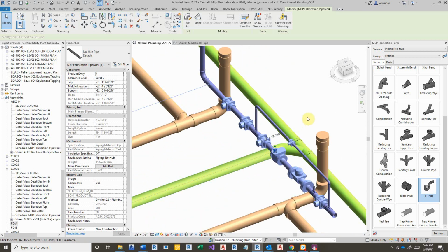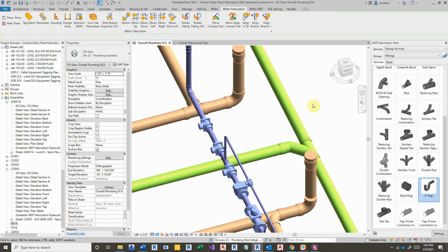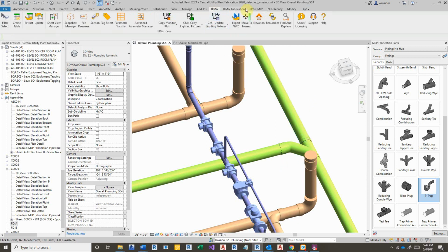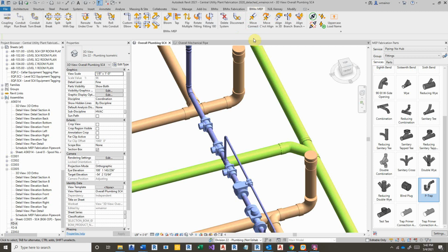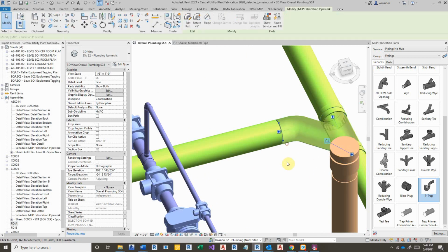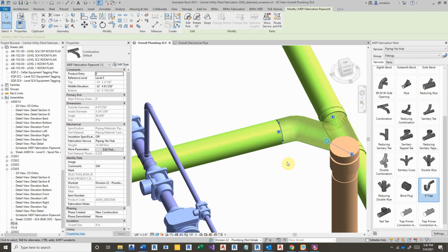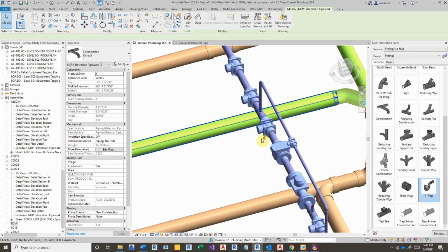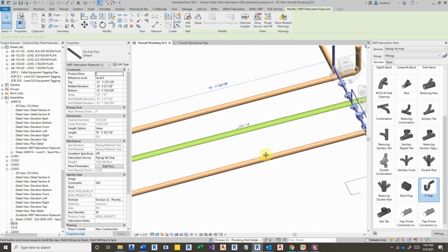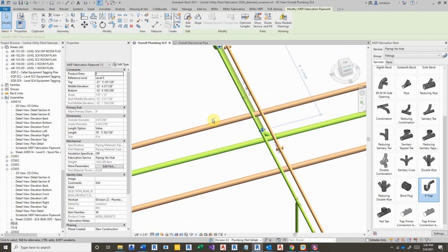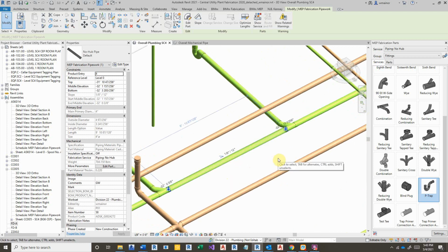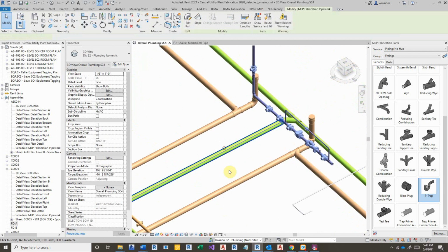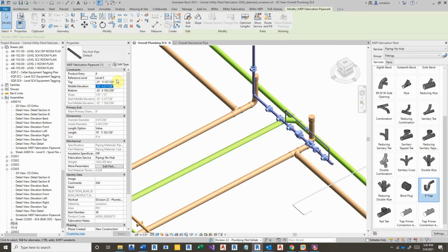because we have tools that are going to allow us to break connections. So we've got a disconnect command on BIMrx MEP that allows me to come in and click on two fittings, and it breaks the connection. In this case, breaking the connection removed the O-clamp. But now I've compartmentalized my system. I've broken it up into smaller chunks, and I can come down rather upstream and just verify that all the slopes are true. Then I can adjust my elevation.